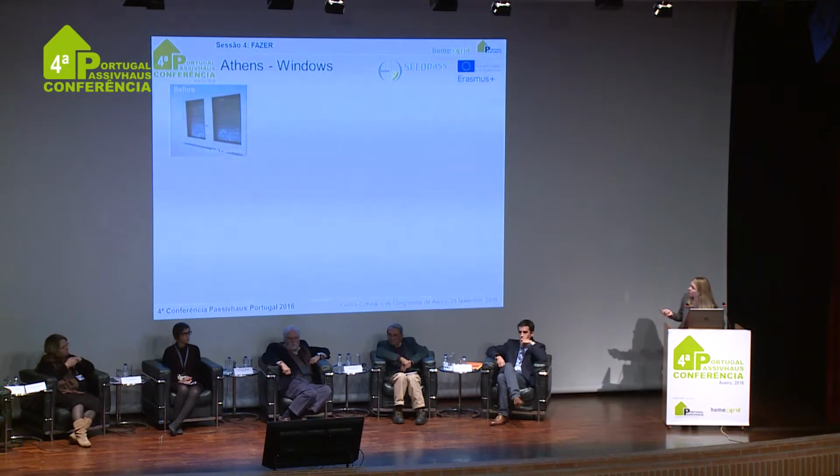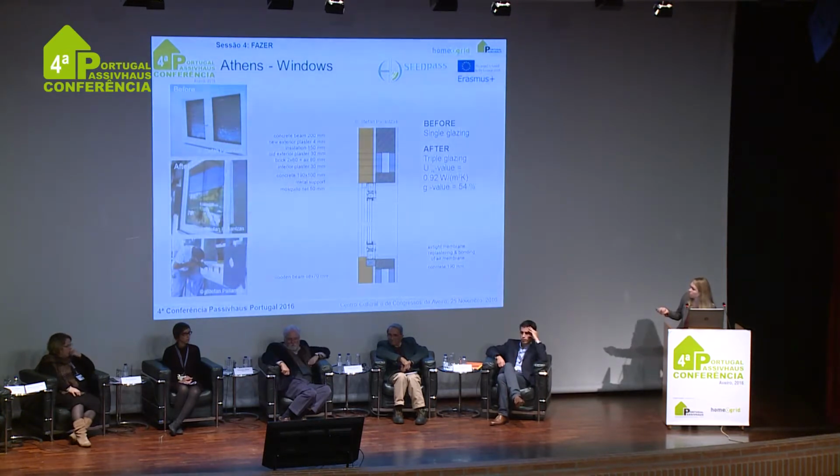Regarding the windows, before he had some wooden windows with double sash. He changed them with single sash windows so he can enjoy more solar gains. And before he had single glazing, now he's having triple glazing. And you can see here he's installing it in the insulation layer to limit the installation thermal bridge, which is what we usually recommend.